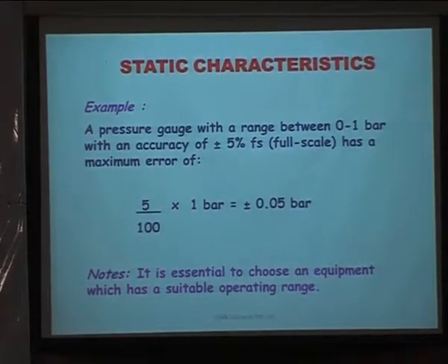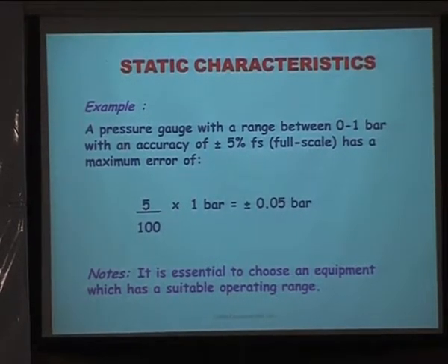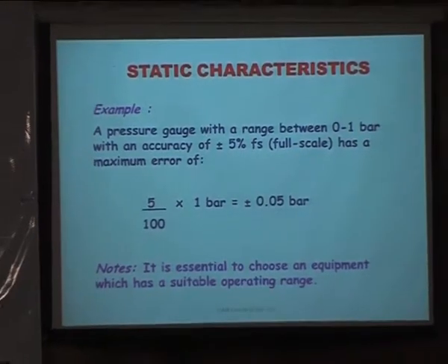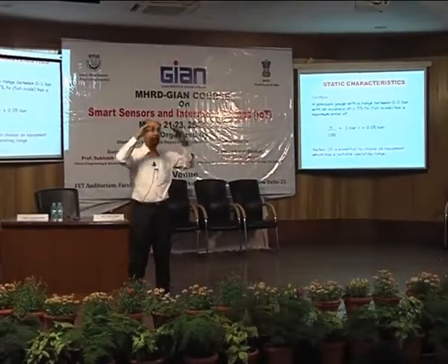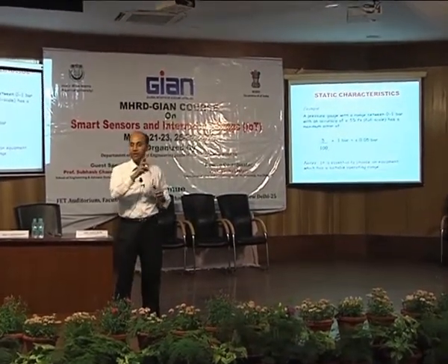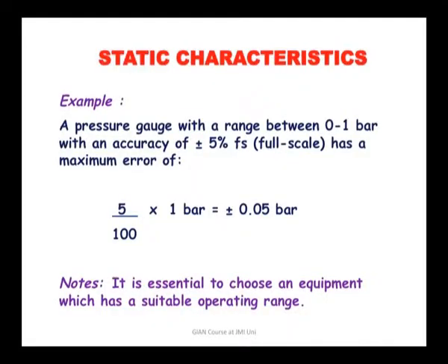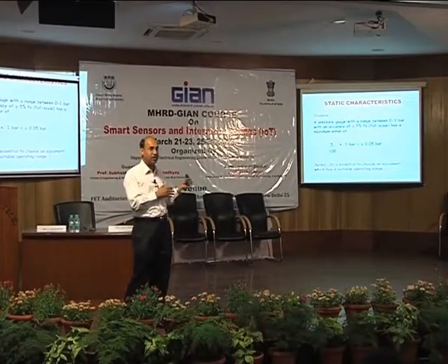So what it means is that we need to accept some error. That error we can calculate as 5% accurate, so plus minus 0.05 bar. That's the absolute value you have to take. So you know what the ideal value you should get is. You measure. If the difference is within that, then you say it's fine. But if it is outside the range, then the accuracy they are telling, plus minus 5%, is not correct. Okay, they are actually bluffing something else, which is not the correct value.